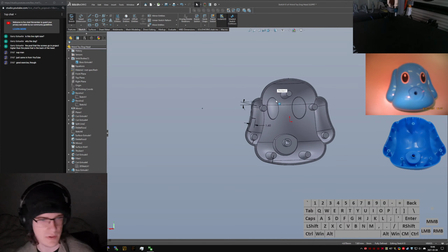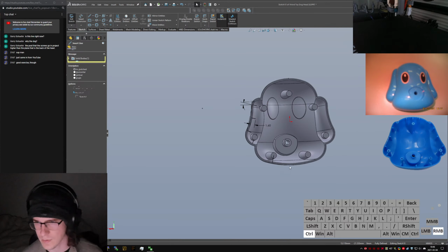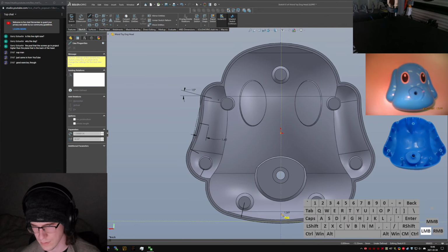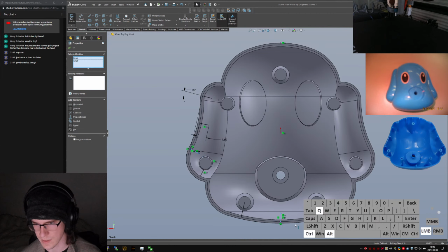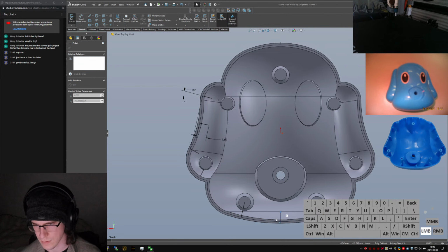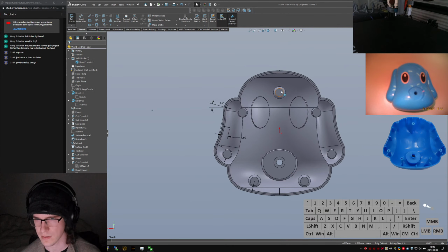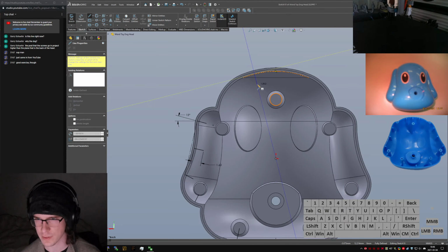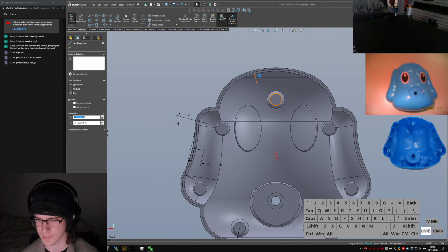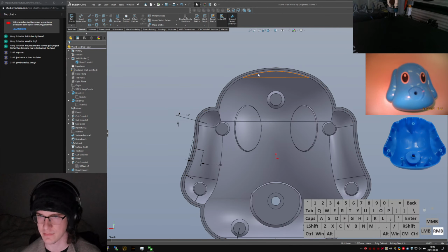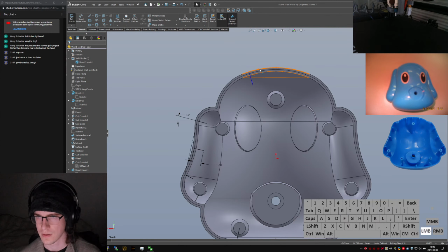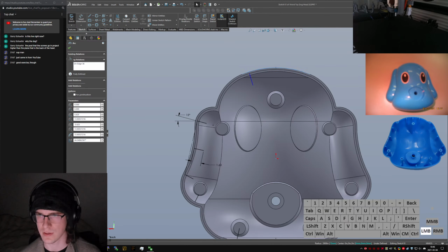What does that leave me with? We got another short stubby one here on the bottom. Make that the same length. Cool, that one's fully defined. We've got 3 quick short ones across the brow. Oops, that's from the wrong point though. Needs to be from this midplane because otherwise you could get weirdness. We'll quickly convert that.